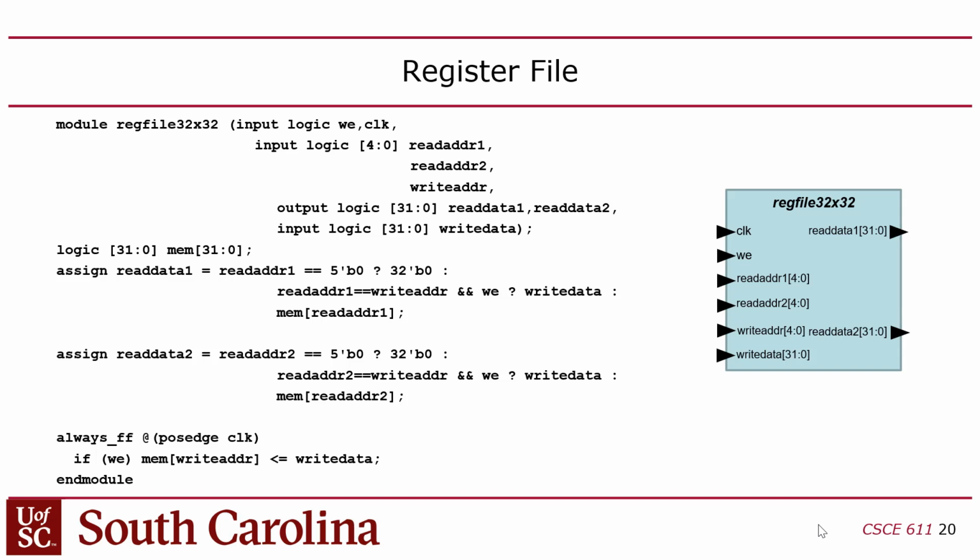You actually have two kinds of RAMs on an FPGA. There's block RAM, which has 2 ports and has a synchronous read. This has 3 ports and an asynchronous read, so this won't go into block RAM. Then you have something called distributed RAM, which is where you use the lookup tables, which are normally used to create gates. You can use those as a RAM as well, but they only have 1 port. They do support asynchronous read, but we have 3 ports.